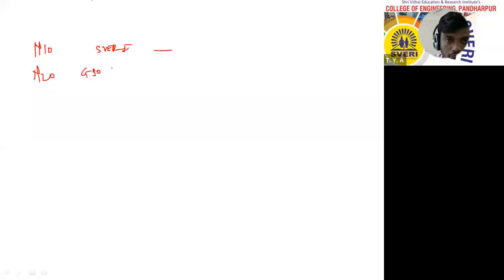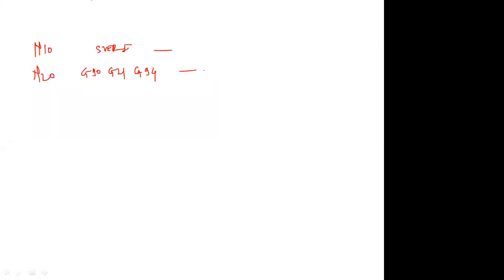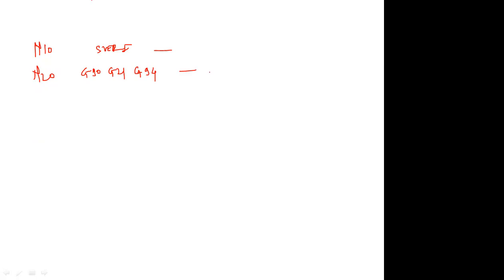Okay. Block number 1, name of program. Suppose we will give this query. No problem. Second block, N20: G90, G21, G94. Okay, description. G90 is the absolute coordinate system.